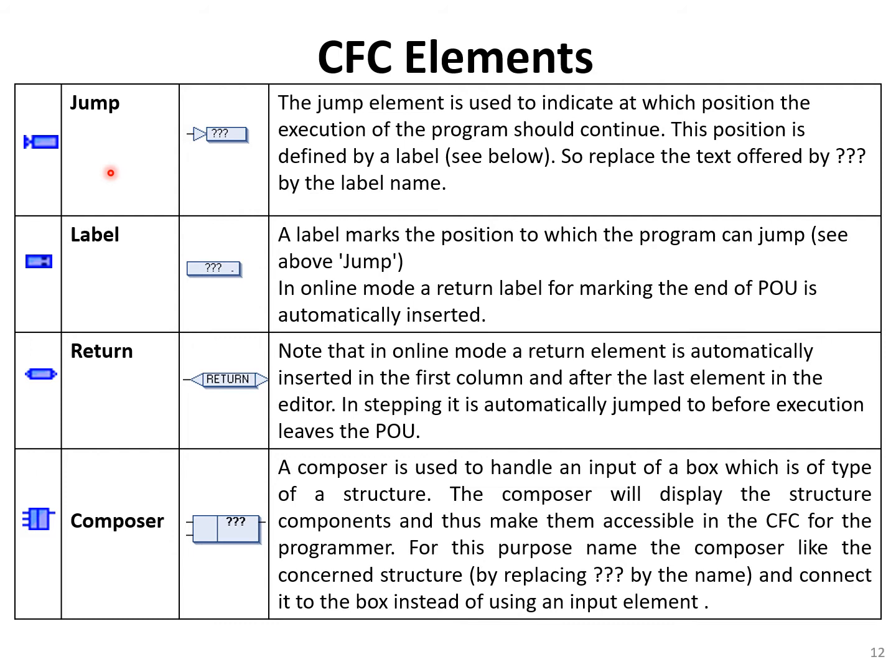Return, again similar. Note that in online mode, a return element is automatically inserted in the first column and after the first element in the editor. In stepping, it is automatically jumped to before execution leaves the POU.